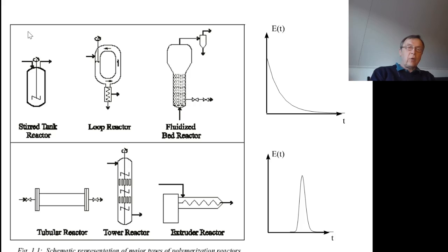The continuously stirred tank reactors are used for a variety of free radical polymerizations, again of ethylene, but also styrene, butadiene, and loop reactors are used for polymerization reactions that are operated at very high concentrations, because at high concentration we also produce a high heat flux, and from such a loop reactor a lot of heat can be removed from each single volume element of such a reactor.